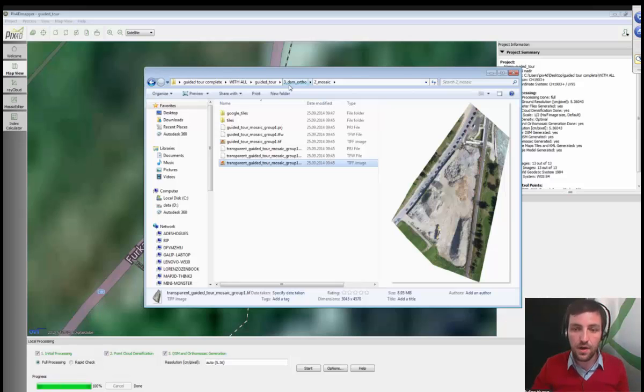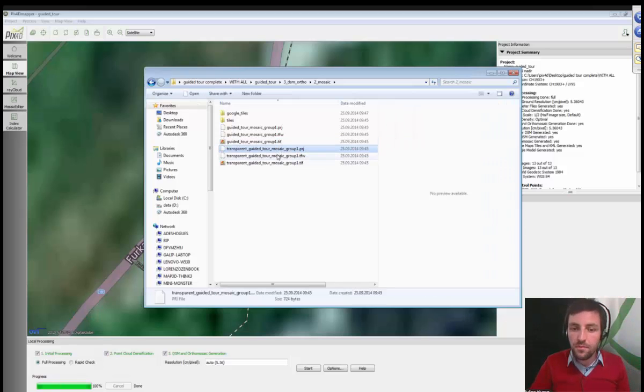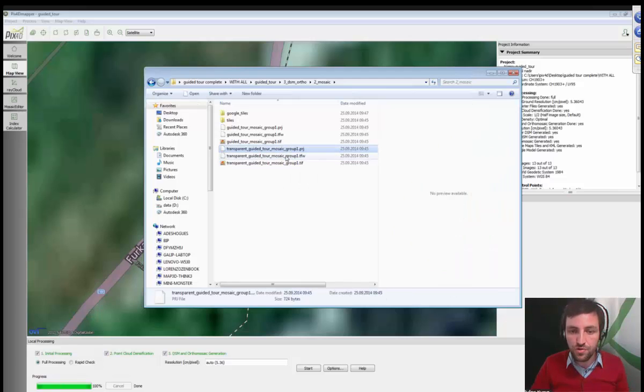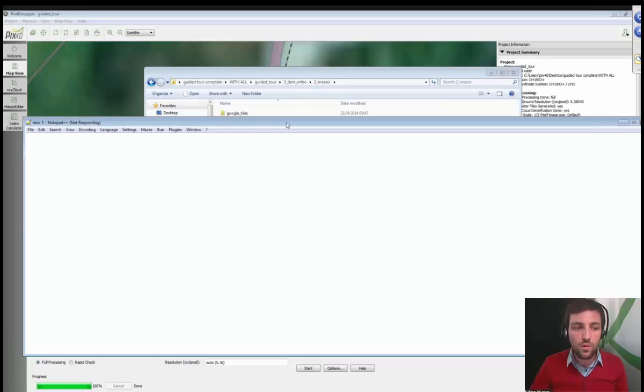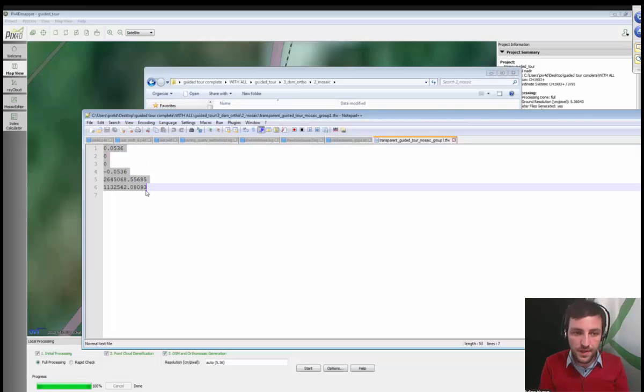All these files I just mentioned are georeferenced, because the information is contained in the metadata of these files. There is the information about which is the coordinate system and at which area they are placed. Some older software where you need to input these files are not always able to read the metadata inside of this imagery. So that's why we also generate these .prj and .tfw files, which are simple text files that you can open with a notepad, for instance. These files contain simple information about which projection system was used and what is the location in the world using this projection system.